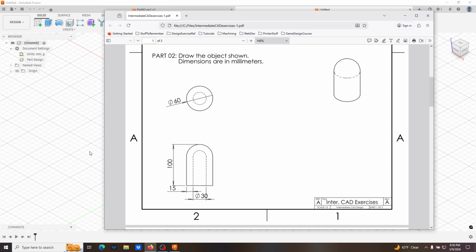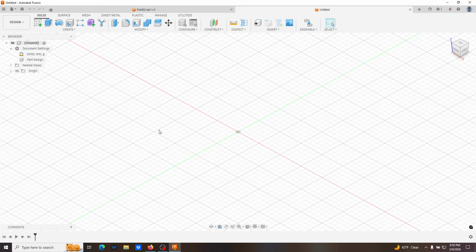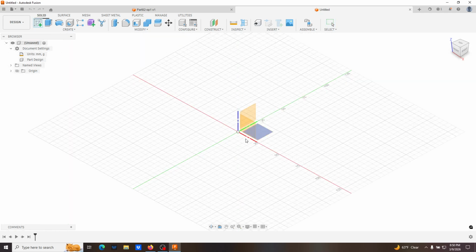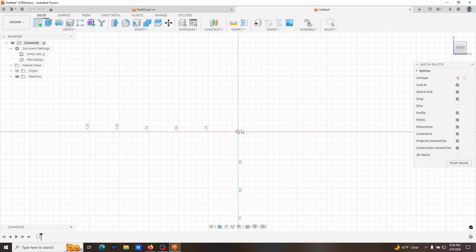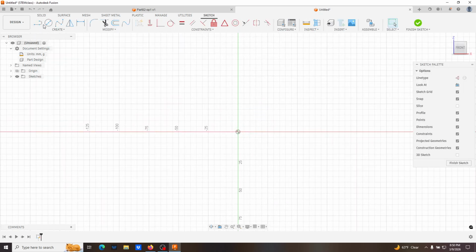So one of the things is that whenever you're doing a revolve piece, you're basically cutting it in half and using an axis that lies on the edge of it. So again, not that it really matters with my plane here, but I'm just going to use this one. And then I am going to draw kind of a half cutaway of it.